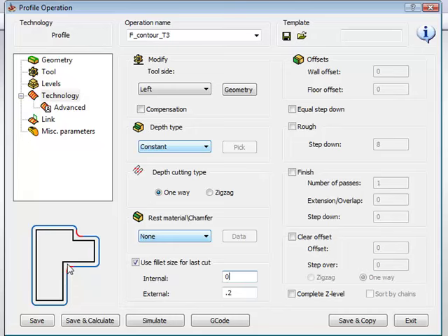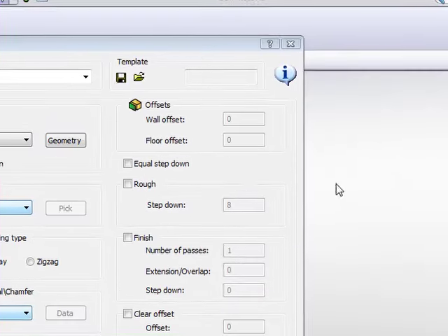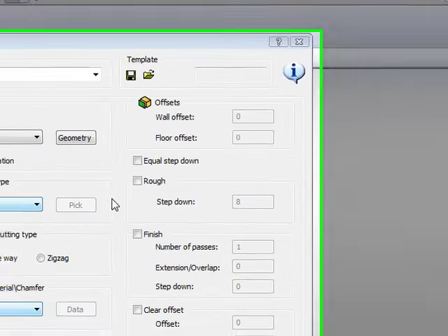If my tool radius is the same size as my radius over here, or larger, especially when you have a sharp corner, it'll create the center tool path with a slight radius, thereby not putting extra pressure on this wall over here. So I can put, if I need, say 0.2 millimeters as well. We'll now move over to the right hand side of our screen.